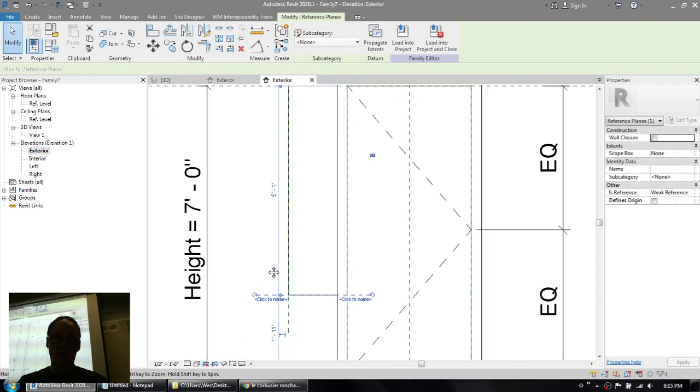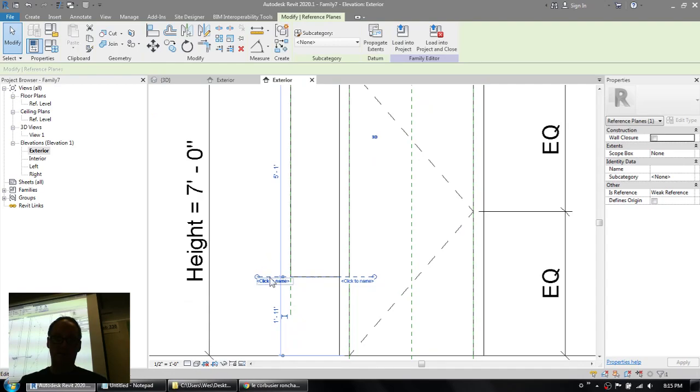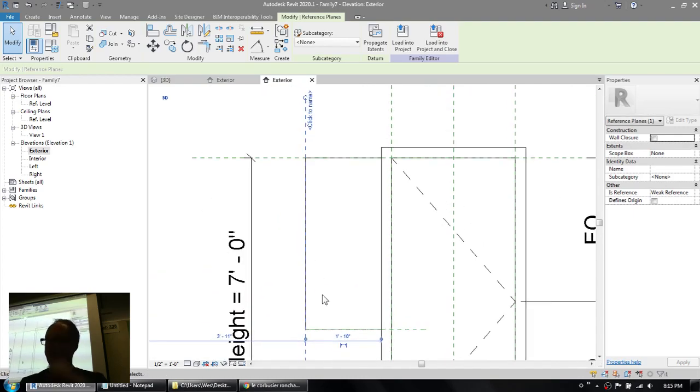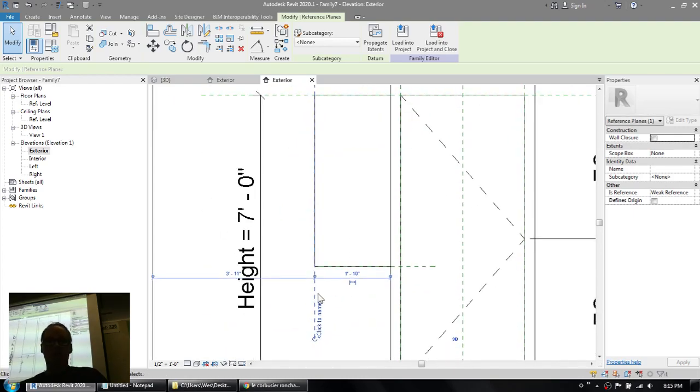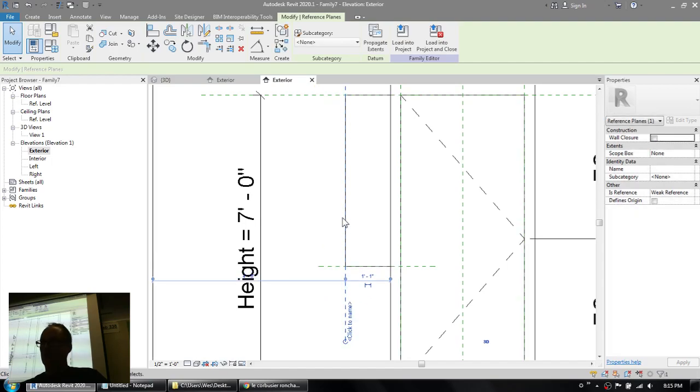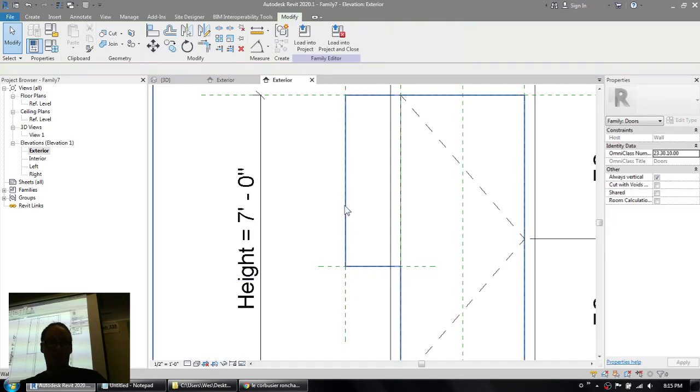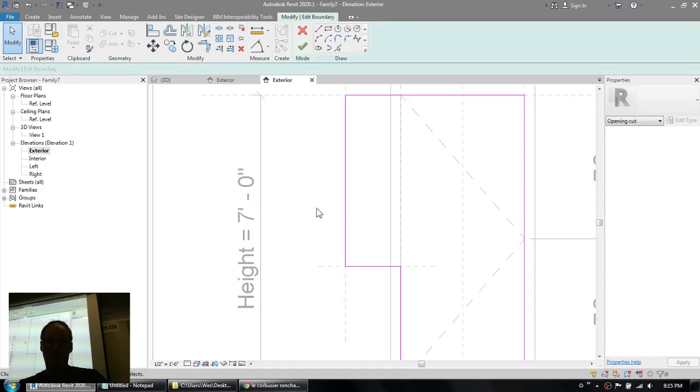Okay, so now watch what happens here. I'll move this reference plane around. And you can see the openings changing there. It's getting bigger or smaller based on wherever I drag that to. But look at this. The opening changed even though that particular pink sketch line, if you will recall, wasn't locked to the reference plane. So if I just hover, tab to get the opening, and then I think I could double click it. Yep. So this particular sketch line here, this one has been locked.